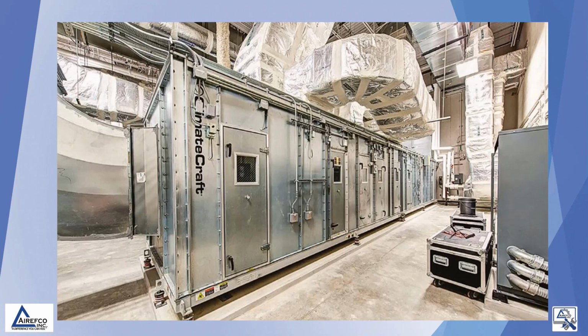When he opened the door, he said, "I see what the problem is. The static of the blower is overcoming the drain, and it's pulling the condensate out of the drain and not allowing it to flow out of the condensate tubing." So we had to put a bigger trap on that unit, and once we did that, it drained correctly and there was no more water on the floor.